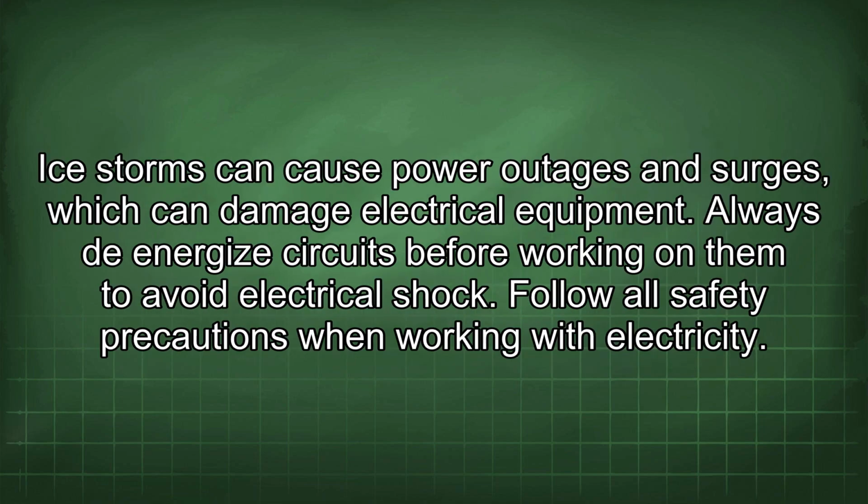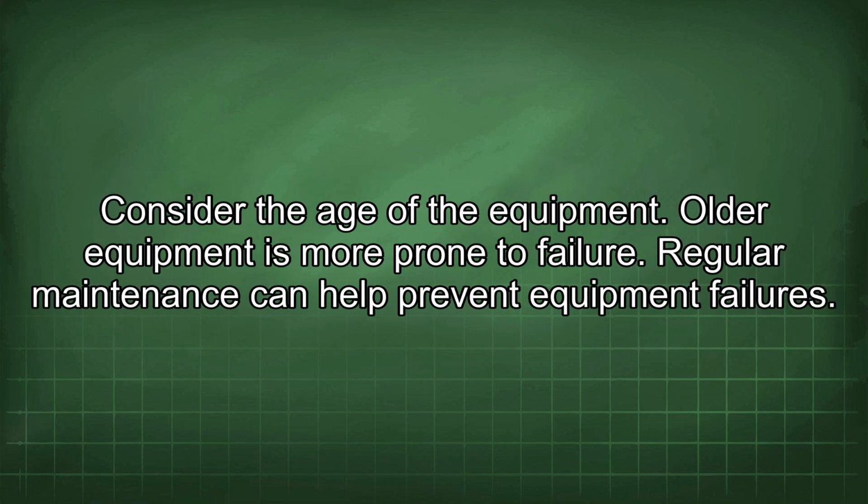Ice storms can cause power outages and surges, which can damage electrical equipment. Always de-energize circuits before working on them to avoid electrical shock. Follow all safety precautions when working with electricity. Consider the age of the equipment. Older equipment is more prone to failure. Regular maintenance can help prevent equipment failures.